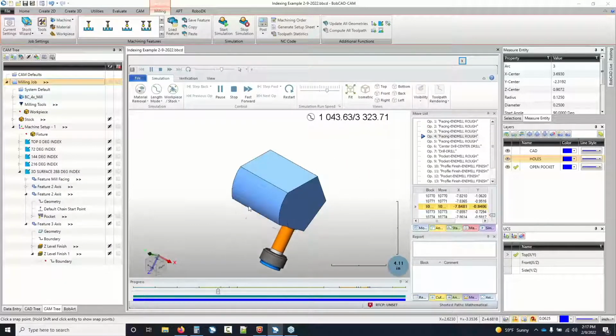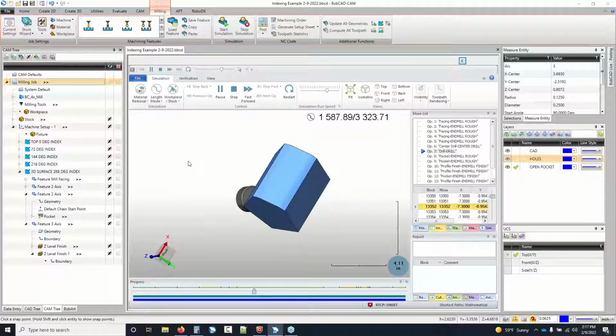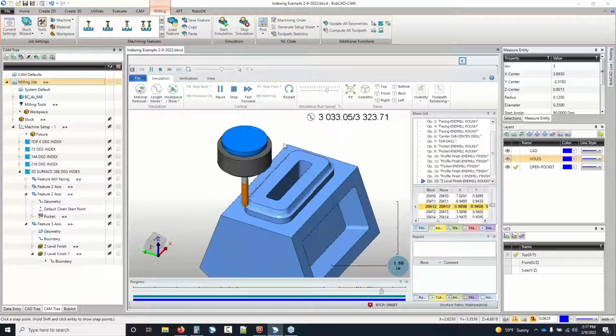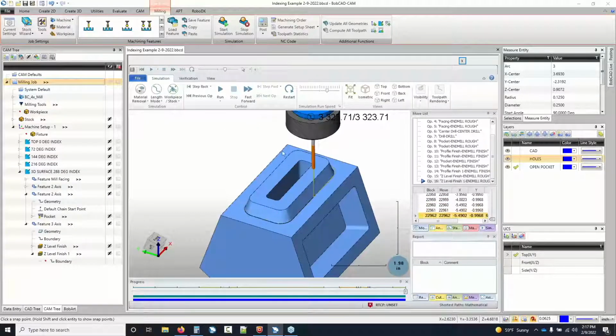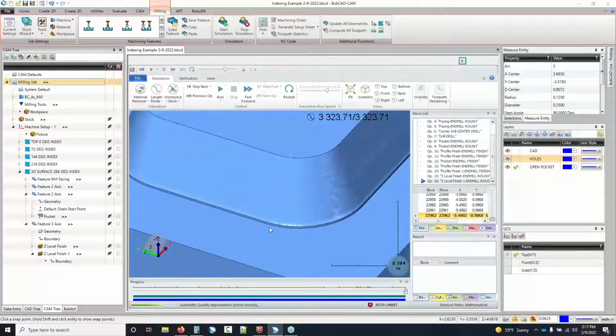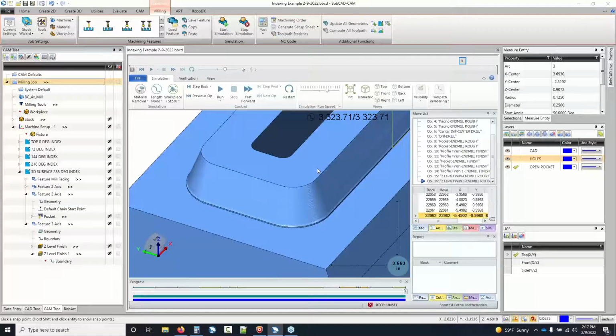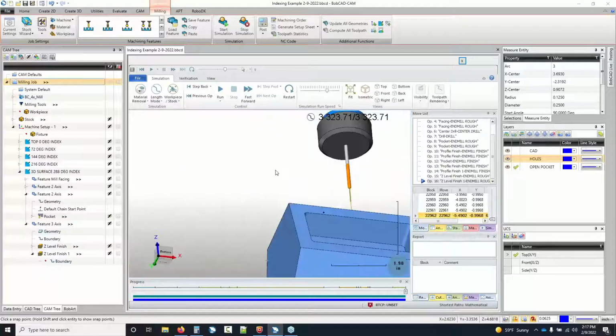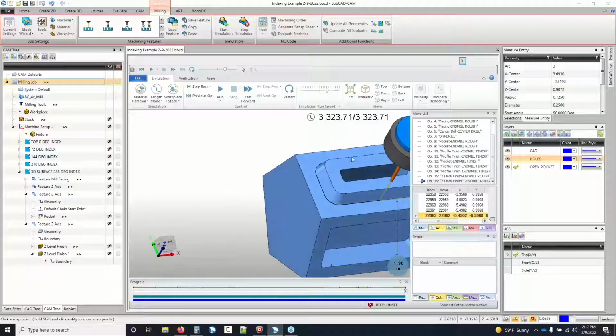So I want to look at, I believe this side is the one we want to orient up. That's what we'll have up. There it is. So you'll see, even with the smaller one, we still have a little radius. Again, the right way to do that is to add whatever acceptable fillet you could put in there, or you'd have to get a tool that matches that taper and has a flat bottom, but I'm not going to calculate all that. So there it is. That's our part.